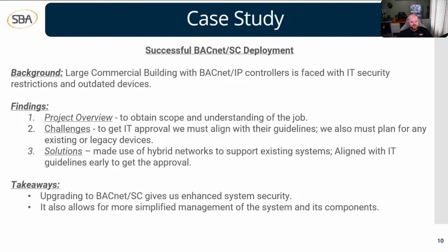In order to get our approval from the IT department and upgrade our controllers, we made use of hybrid networks to support existing systems. A hybrid network, in this instance, means we've got controllers that are BACnet SC, we've got controllers that are BACnet IP, and then maybe some that are BACnet MSTP too. So a hybrid network is just multiple different protocols on the network talking together.